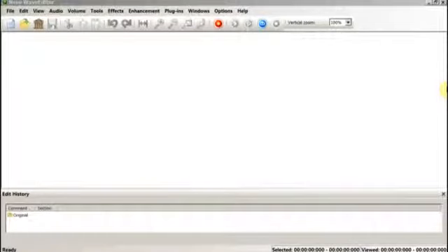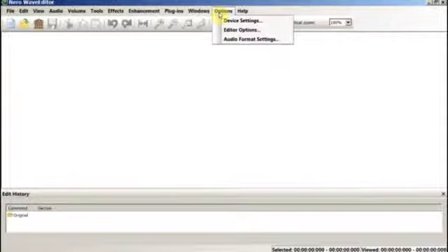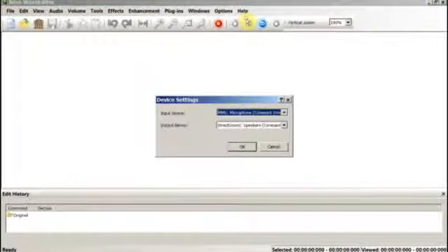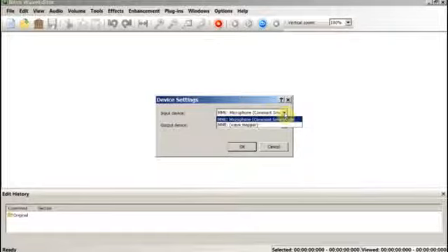When the devices are connected together, open the Wave Editor. Then go to the command line and select Options, Device Settings. If a USB headset is being used, it will have its own sound card, so this will need to be recognized as the input device. Otherwise, there will only be the onboard sound card of the computer in use.